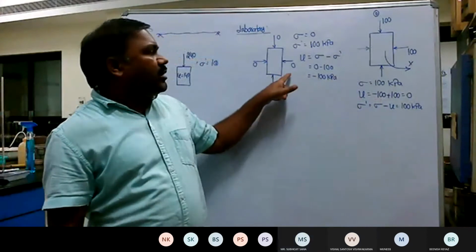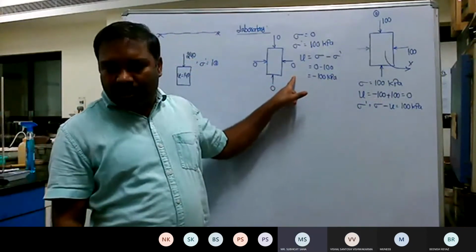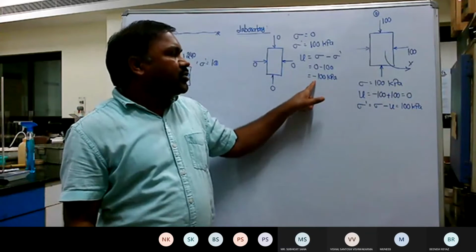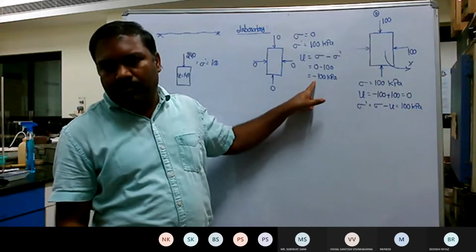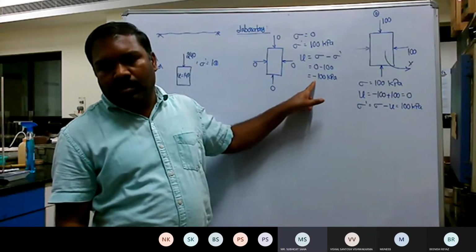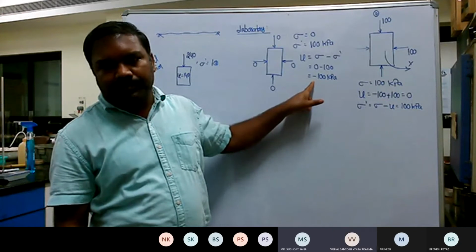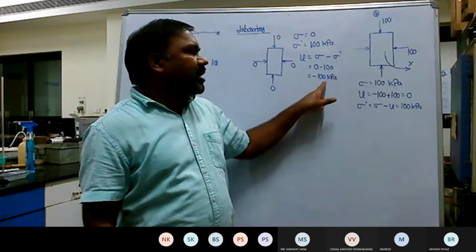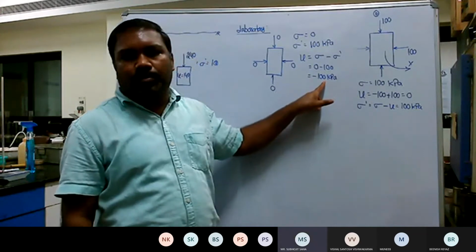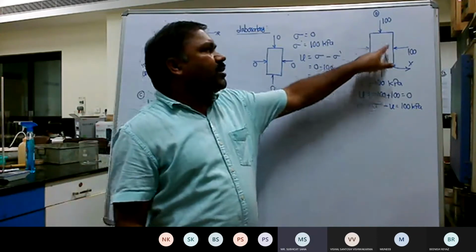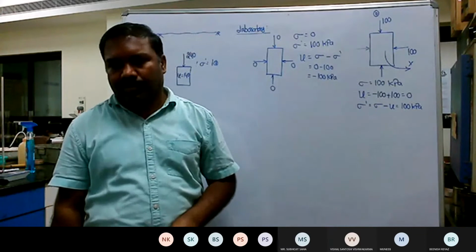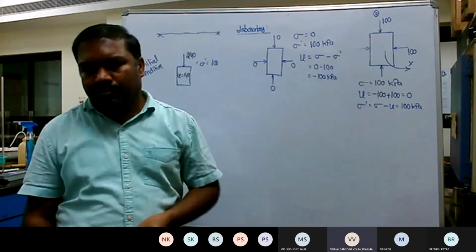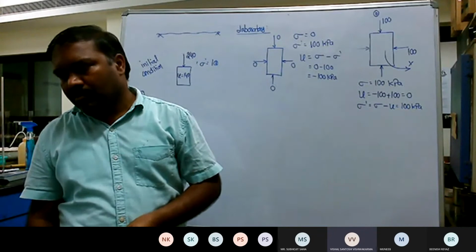See, initially when you brought the sample to the laboratory, the pore pressure within the soil sample is minus 100 kilopascals. Now, against this pore pressure, you are applying a cell pressure of 100 kilopascals. So, sir, all the cell pressure is converted into pore water pressure.